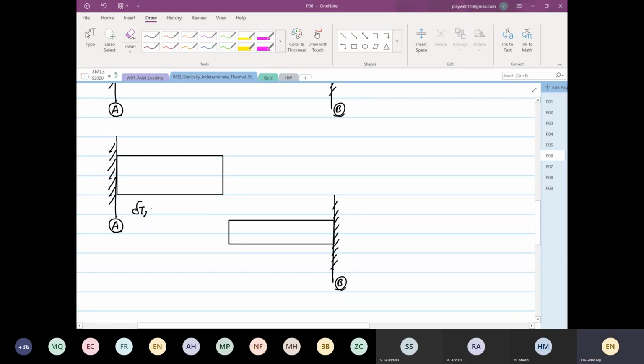of the aluminum. So this is equal to 23 times 10 to the power minus 6, multiply by change in temperature, 140 minus 20, right? So T1 is your new temperature. Your reference temperature is T0. And then the length is equal to 0.3. So this will be equal to 828 times 10 to the power minus 6 meters. So this is for the aluminum.